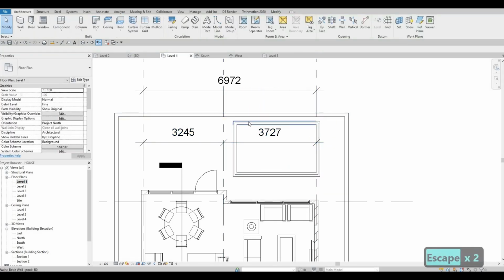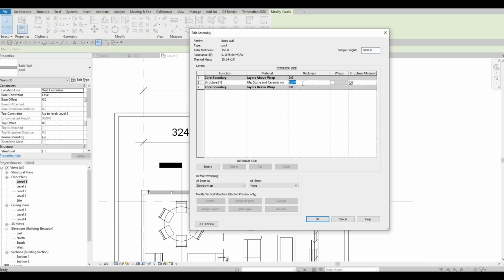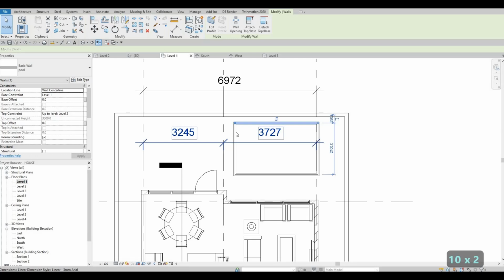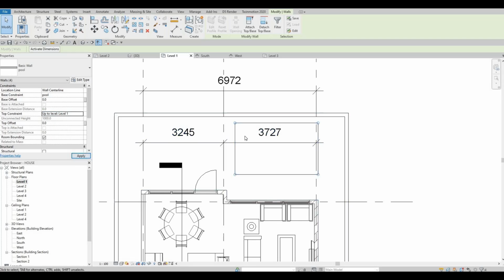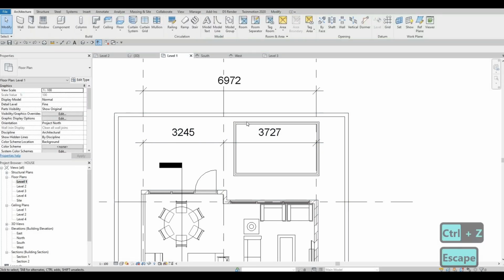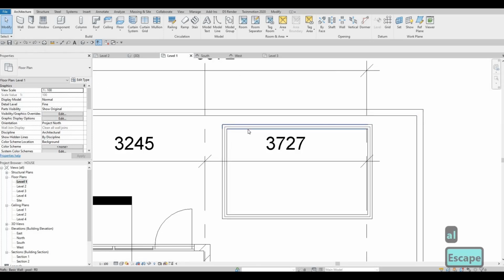and then this one we could also edit the size, so make it 100 thickness, and then here we could select everything, and the base should be on the pool and level 1, so we need to change that a bit, but let's undo that, and then before we change those, we should just align this to the boundary.